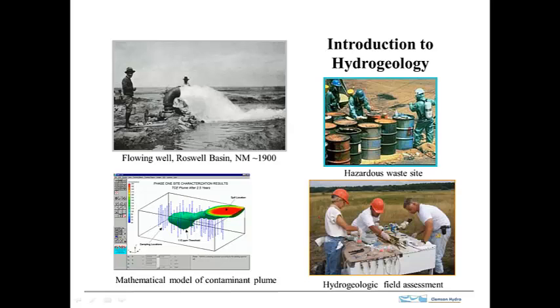Here is a model of a plume. There was a source right here, and this is the subsurface, and you can see the plume is headed down in that direction. Each one of these blue dots is one of the samples similar to what's being obtained here. So we get this three-dimensional structure that forms this groundwater plume. And so understanding how the plume moves and ultimately what might be done to stop the plume or destroy the contaminants in place, those are some important applications for hydrogeology.